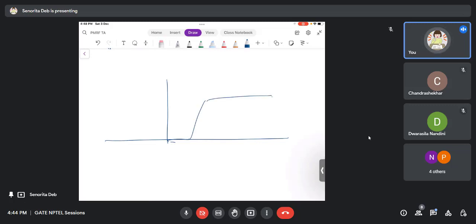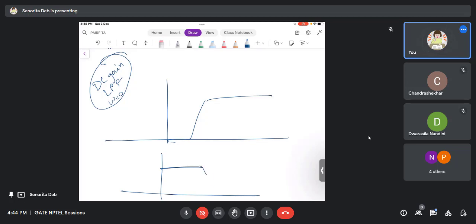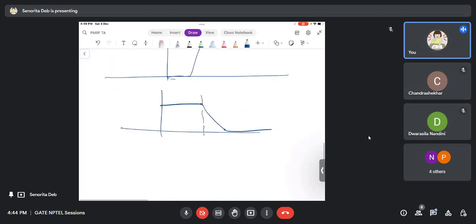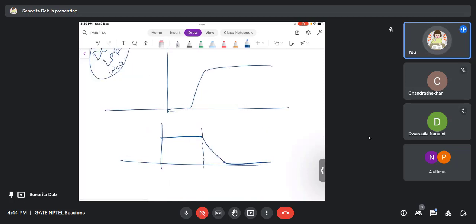So you are actually getting confused because I mentioned the term DC gain. The DC gain is only applicable for low pass filters, because we are talking about omega equals 0. And only in this kind of case do we talk about DC gain. We don't talk about DC gain for a high pass filter. And also in normal amplifiers,